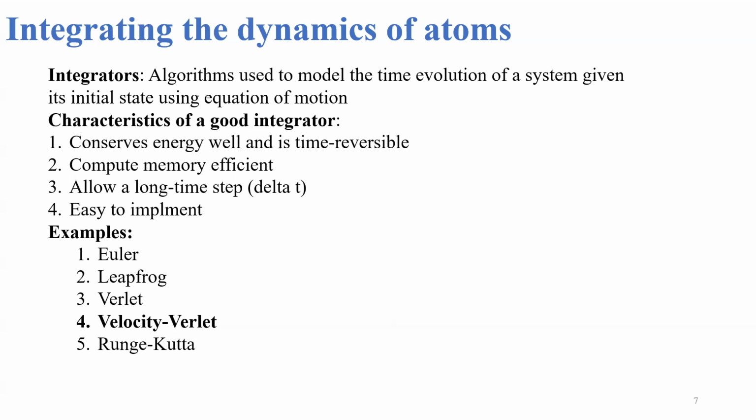If you remember, when we were solving the finite difference equation in the mathematical foundation or programming foundation module, there we had to choose an interval h, right? So here in this case, we have the time step, t basically. The smaller, the better. But if you have a very small time step, it might take a longer time to simulate a large time scale.